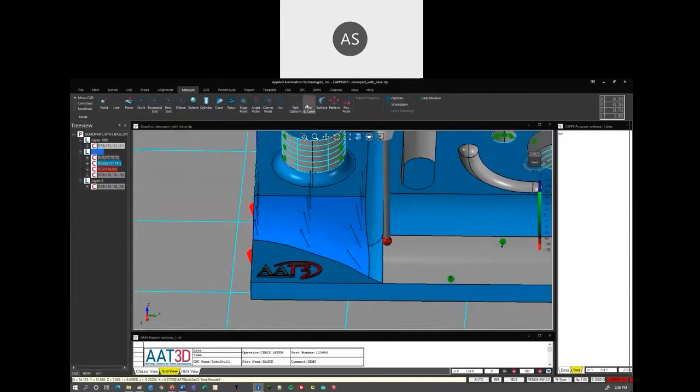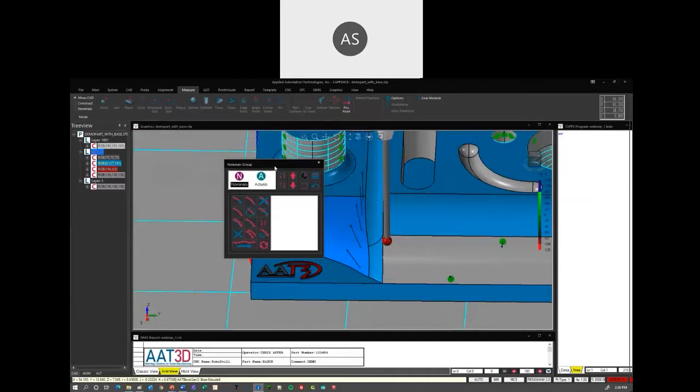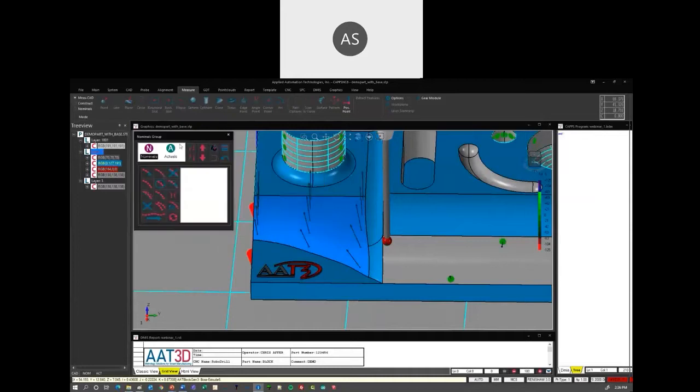So down here in the measurement toolbar, we have this option here called path options. When I click on this, this is going to bring up my dialog for what we call nominals grouping. Okay, I will then use the select box option. I have different options. I could do teach, pick the points in any order I want. I could do generate, where I pick the first, pick the last, and the software will go numerically through the points. I can select all. I can eliminate a path once I make a path, or I can use box. So I prefer to use box.